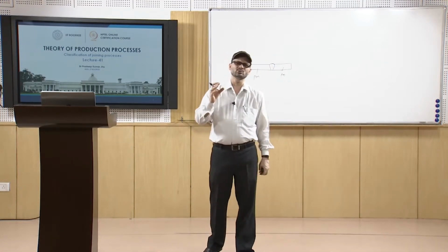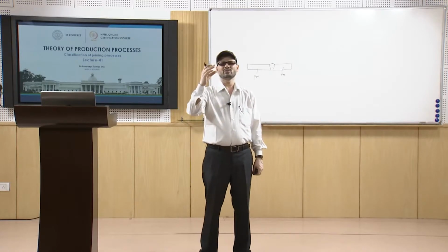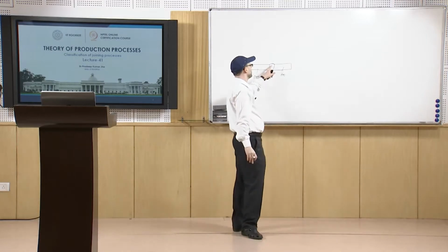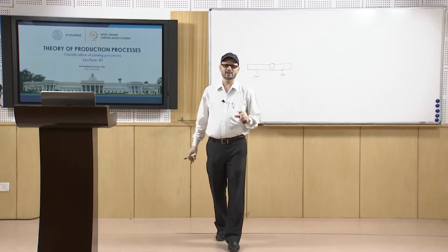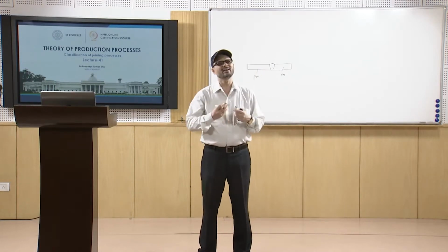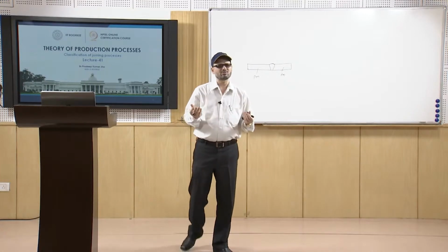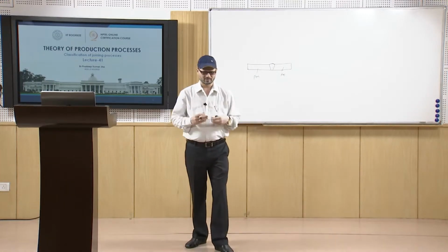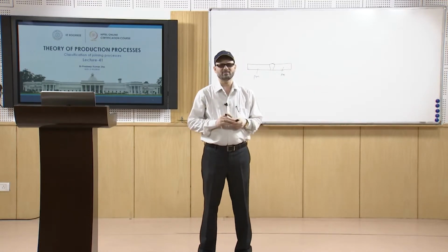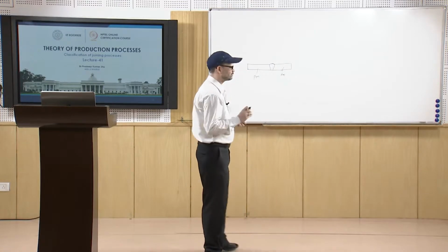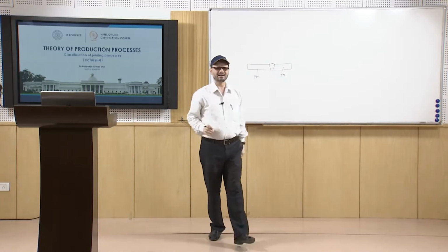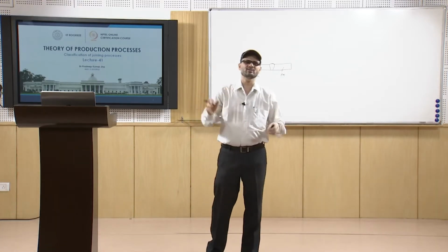So, it is basically used for specific purposes where you are just working for the sake of holding its shape. In the soldering case, the melting temperature of solder alloys is even less, so the strength is even less, but that is normally the requirement. Mostly whenever you go for electronic areas like printed circuit boards, in that case of joining you go for soldering, because you just have to add them, just to join them. So, strength is not the criteria.